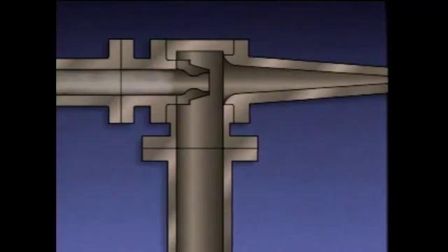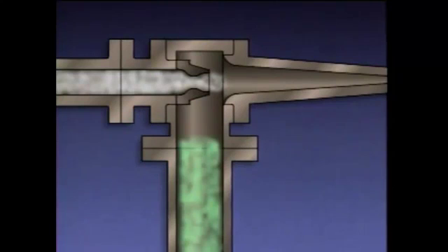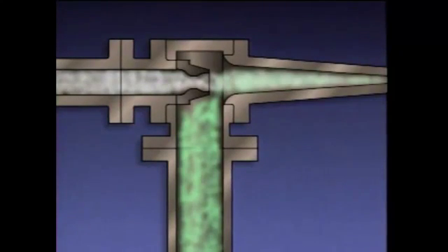During operation, high-pressure steam flows into the nozzle inlet of the jet pump and passes through a restriction in the nozzle. This causes a low-pressure area to form just past the nozzle. The low pressure draws the gas being pumped in through the pump inlet and into the combining chamber where it combines with the steam. The mixture then flows out of the jet pump through the discharge section.